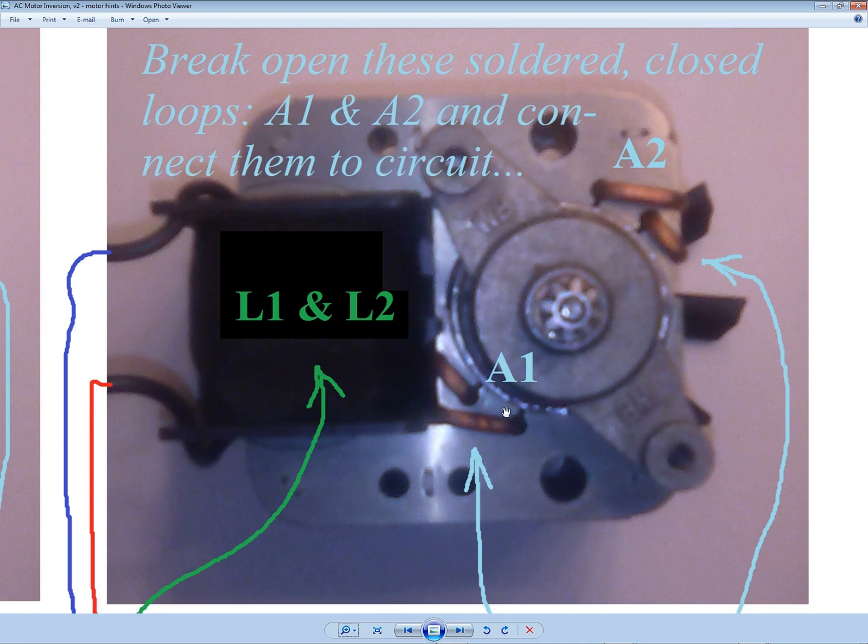Okay, 2 separate solar panels. You can buy them as toy kits, 1 volt, or comparable from eBay, because that's all you're going to need, a couple of volts. Put them in series to give yourself a couple of volts. That's all you're going to need to power this motor.